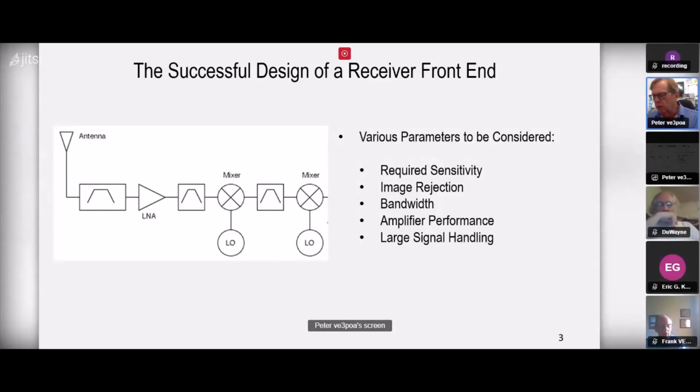Include low noise amplifiers at the front end to amplify weak incoming signals in order to maintain low noise figures. Choose an LNA with a high gain and low noise figure. And in the case of the Phoenix, we use the LT1253 chip, which has 2 op amps in the one package.